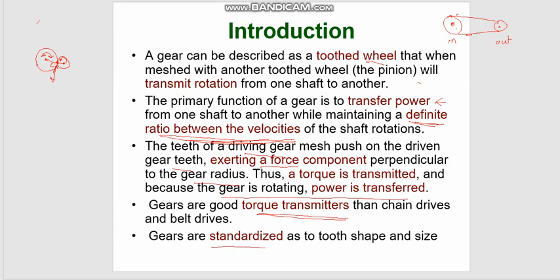Gears are standardized as to tooth shape and size. So whenever you design a gear, don't create your own tooth shape or size. It should be standardized. You can open up a handbook on gears and find various shapes and sizes of gears. So you just follow what's been standardized.